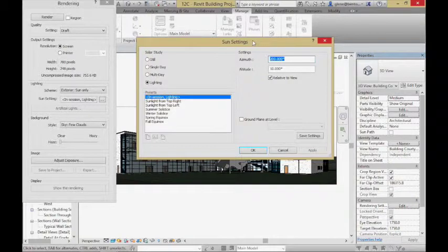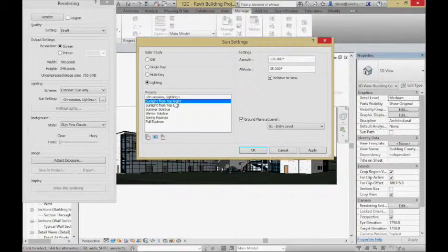There is the notion of just putting the sun at a point in the sky, someplace with an azimuth and an altitude relative to where we are right now. So this is putting it at 200 azimuth, 10 altitude. Let me go ahead and switch it to something else, like just from the top right. That's 135. So I think that is, if straight ahead of me is 0, 135 degrees over. So 135 is kind of over my right shoulder.